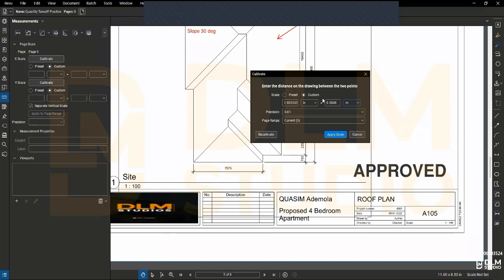That's how you deduct openings in Bluebeam Revu. There's no magic tool that tells you to automatically deduct for doors and windows. You type that by yourself. So as you get the total area in that markup sheet that I showed you, total area of windows, total area of doors and the lights, you will now press so minus so to give you so in the calculator. You can always put that directly in an Excel sheet to give you that value. I hope you understand.